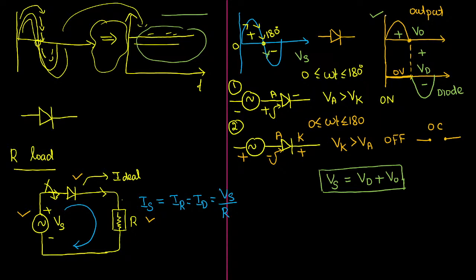If you observe, with respect to the time period, the output voltage, see there. From 0 to 180 degree, we have positive voltage. After that, from 180 to 360 degree, it will be 0. Again, after 360, the same waveform will appear once again. Again after 180 it will be 0. Like that, I am getting only positive polarity. So DC means a single polarity. Either you can carry positive or you can carry negative, but we can't carry both waveforms. So successfully, what I completed is that I can carry only the positive waveform with the help of the diode.